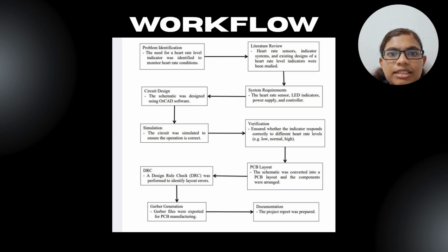After simulating the circuit, we ensured the indicator responds correctly to different heart rate levels. Then the schematic was converted into PCB layout and a design rule check was performed to identify layout errors. Since there were no errors, the Gerber files were exported and the report was prepared.